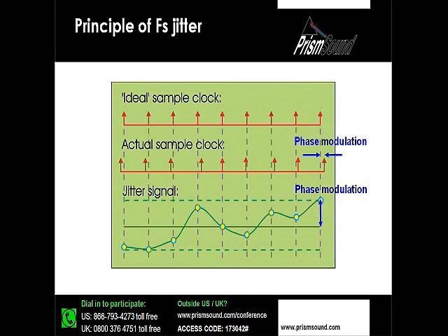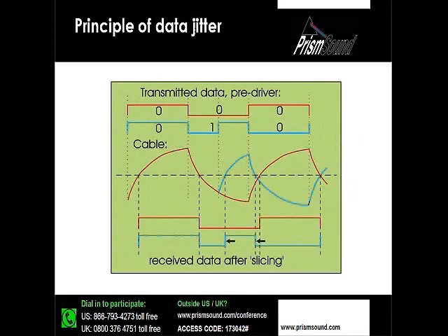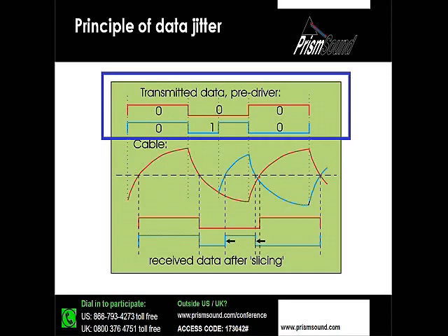Now, this diagram illustrates a form of jitter that is a direct consequence of the interaction between the high frequency losses of the cabling and the clock data embedding of the coding scheme. We've got two alternative segments of transmitted biphase mark encoded data here up on the screen. One's carrying a binary sequence of 000 and the other 010.